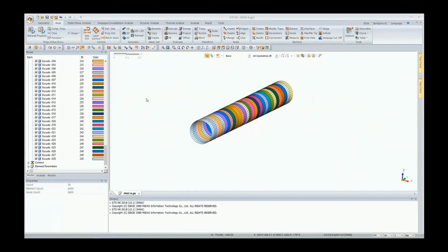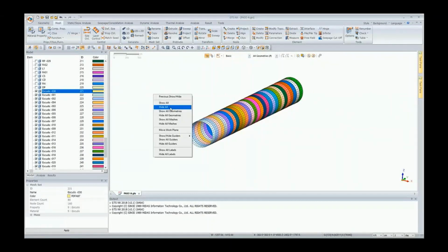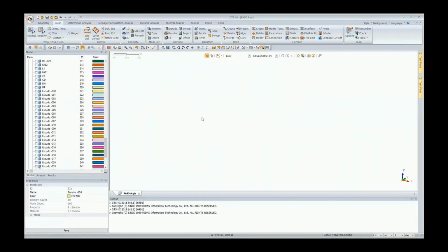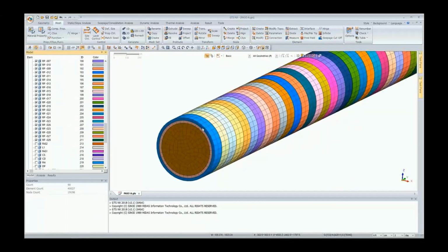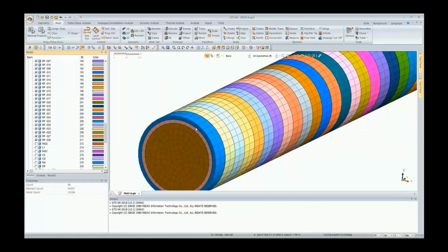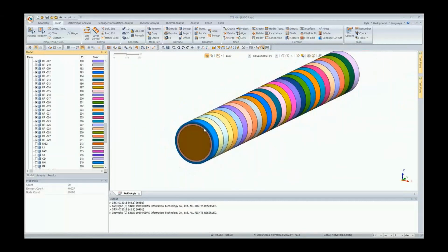So now we're going to move on to apply the pressure loads. We'll start by first applying the front pressure load. For that, we're going to apply that pressure load to both the parts that will be tunnels as well as the support rings. So I'm going to activate those sets. So we see here we have the primary, secondary, and tunnel mesh sets.